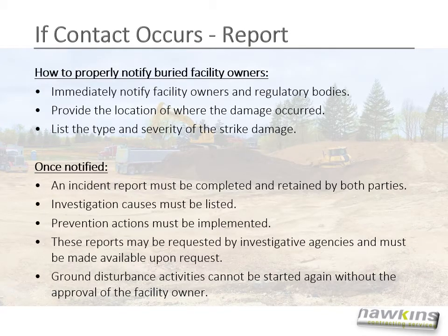When contact occurs, you must report. The process to properly notify buried facility owners is simple but important. Once again, immediately notify facility owners and regulatory bodies. Provide the location of where the damage occurred and list the type and severity of the strike damage. Once notified, an incident report must be completed and retained by both parties.